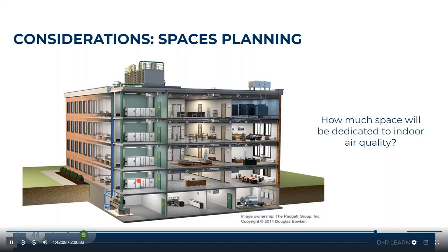One example would be to install a VRF system where all of your VRF systems would be situated on the rooftop, as we saw earlier, and then you just have your inside unit installed, whether in the ceiling grid or on the wall somewhere, which would completely eliminate the need for these huge air handling units and this huge cooling tower and all of this chilled water equipment and hot water equipment located in the basement.